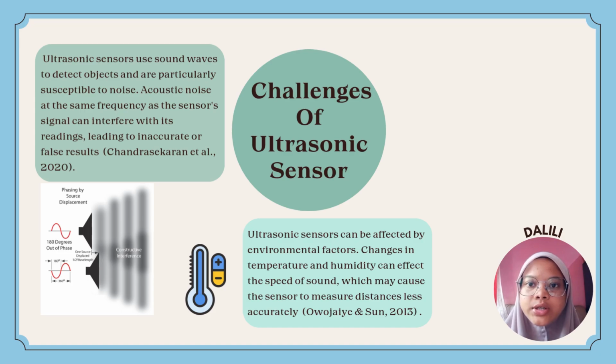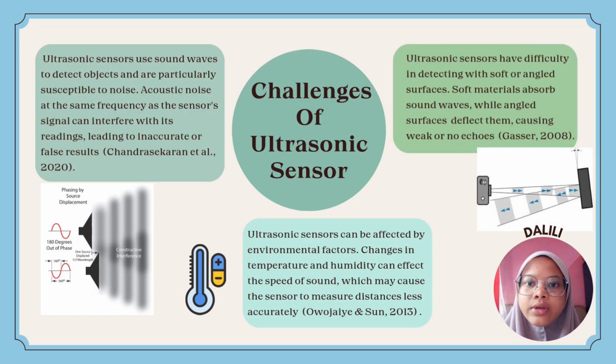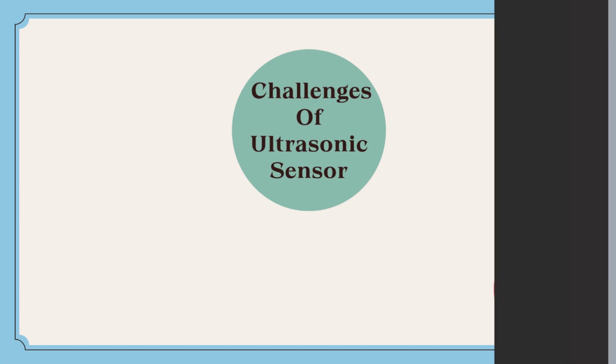The second one is that ultrasonic sensors can be affected by environmental factors. Changes in temperature and humidity can affect the speed of sound, which may cause the sensor to measure distance less accurately. The last one is that ultrasonic sensors have difficulty detecting soft or angled surfaces. Soft materials absorb sound waves while angled surfaces reflect them, causing weak or no echo.